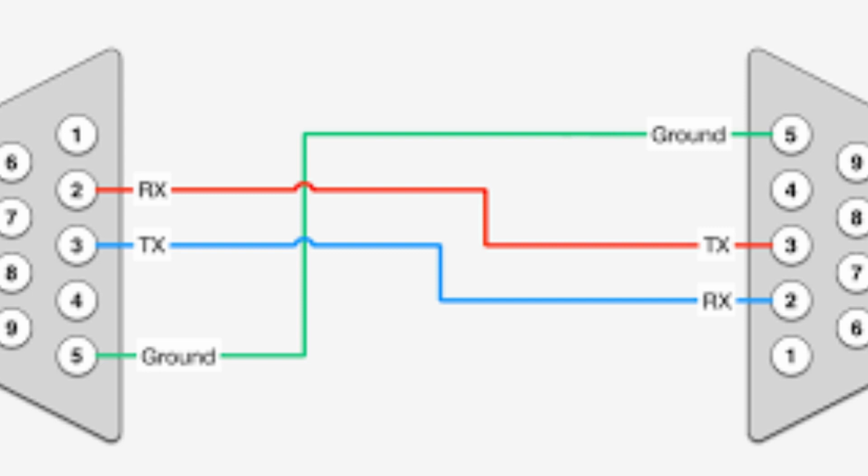Modbus is a protocol that is commonly used with RS-232 for communication between industrial control systems. Modbus defines a packet structure for transmitting data and specifies functions for reading and writing data. SCPI, Standard Commands for Programmable Instruments, is a standardized command set that is commonly used with RS-232 for communication with scientific instruments. SCPI defines a set of commands for controlling instruments and querying instruments' status.